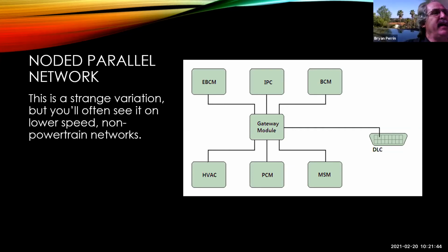Yeah, sometimes it has to do with the protocol. Certainly, if we're talking about these modules, there's no reason to do it. But if this was a LIN system and my gateway was the IPC and I'm talking to all the steering wheel switches, then that's the protocol of the system, so I have to use a gateway. It really comes down to sometimes what protocol. So even though in this illustration we're using module names that everyone recognizes for simplicity, we probably wouldn't ever use this system for these modules.